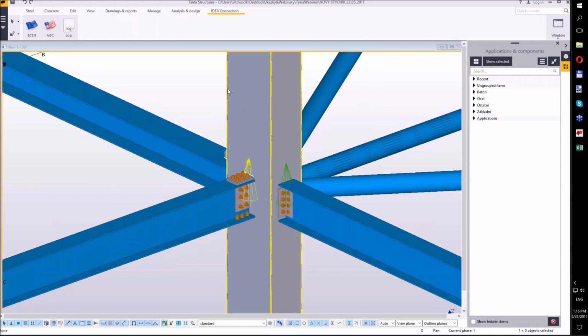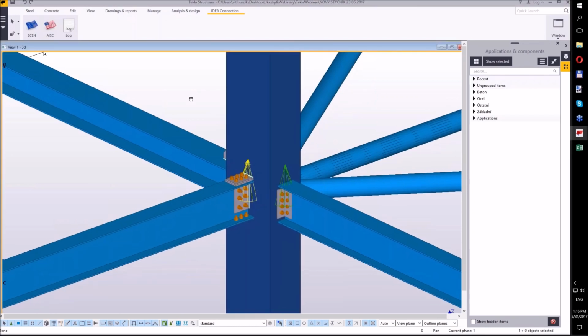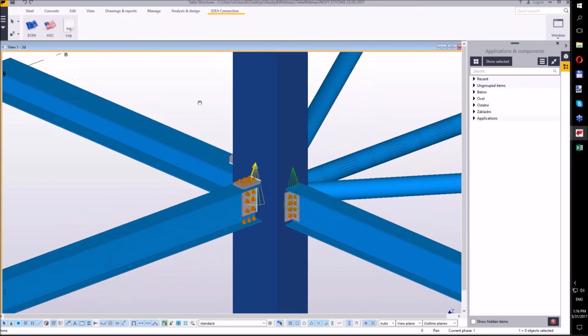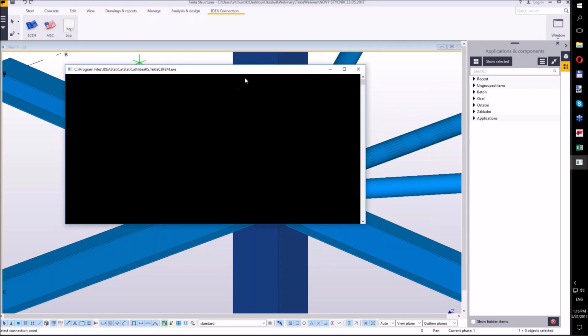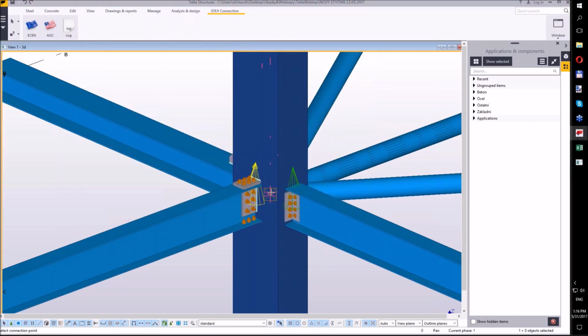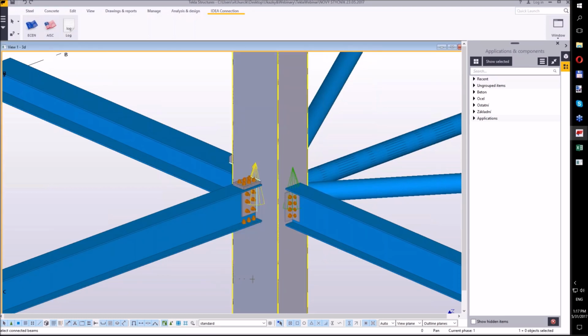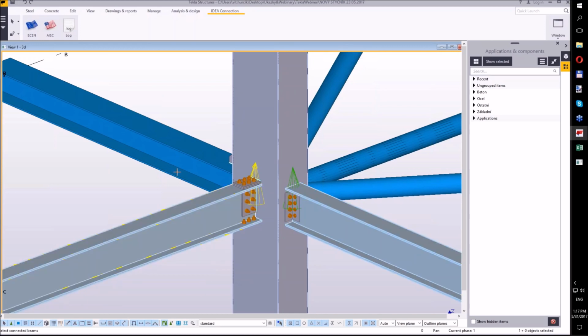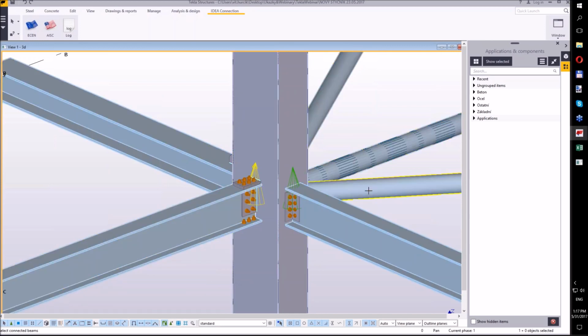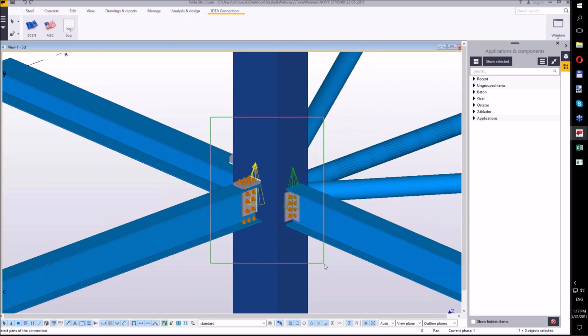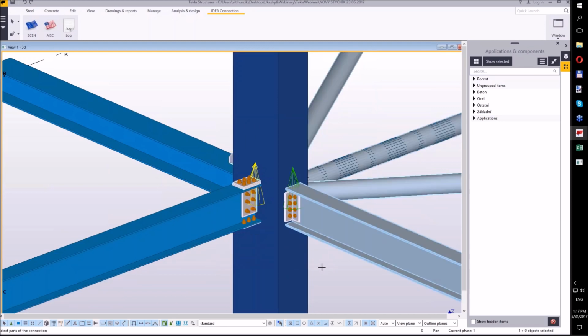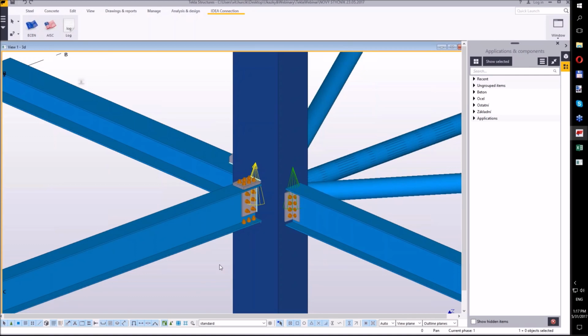Hello. Let's open the project file in Tekla Structures and check this frame joint in IDEA StatiCa. To export it from Tekla, we choose the appropriate button in the top ribbon according to the code which we need, Eurocode or US code. Next step is that we select the point which will be representing the node. Next step is to choose all structural members of the joint. First chosen member will be the bearing one. Last step is to choose all remaining parts like plates, welds and bolts.